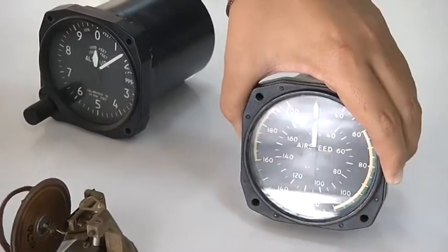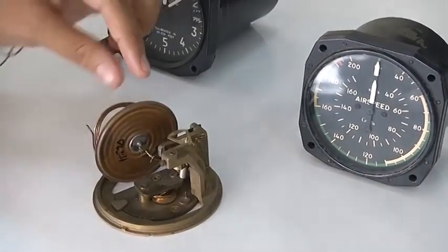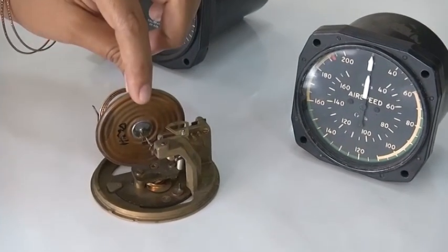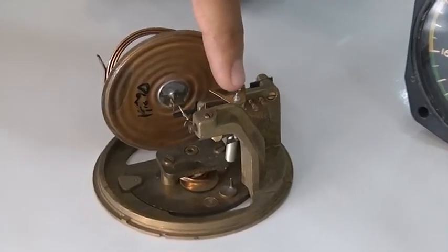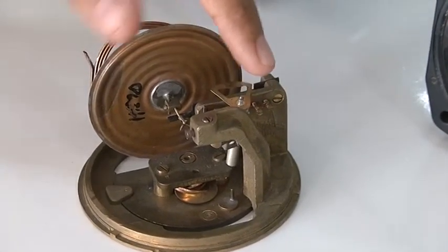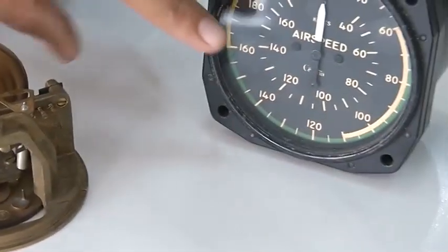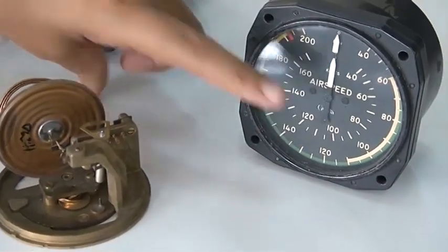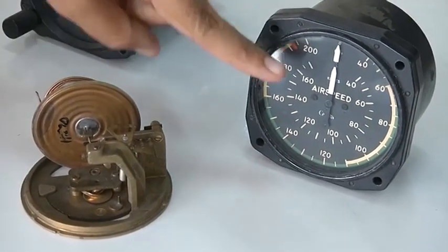Through this the air pressure goes inside, and the difference of pressure is measured through this diaphragm by expanding or retracting it. Then through the coupling element, that is the gears and mechanical linkages, the reading is given to the indicating element on the gauges. Airspeed gauges are calibrated in knots. The difference of pressure when the diaphragm moves is shown on this gauge.